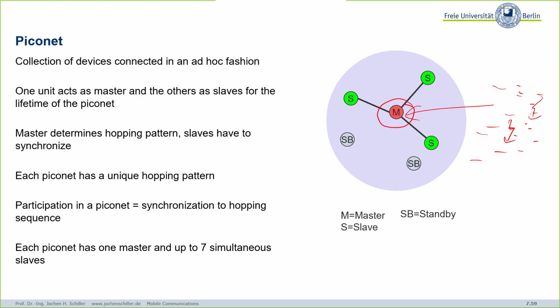Here the question is, what happens if a slave just does not stop sending? Then the slave does not behave according to the standard. That's all. And then the Piconet is destroyed. But it's difficult because then you have to play with the firmware. It's in the firmware of the Bluetooth modules, so you have to change it. But indeed, that's it. Then you destroy it, and the master will not receive it, so you can destroy the network.